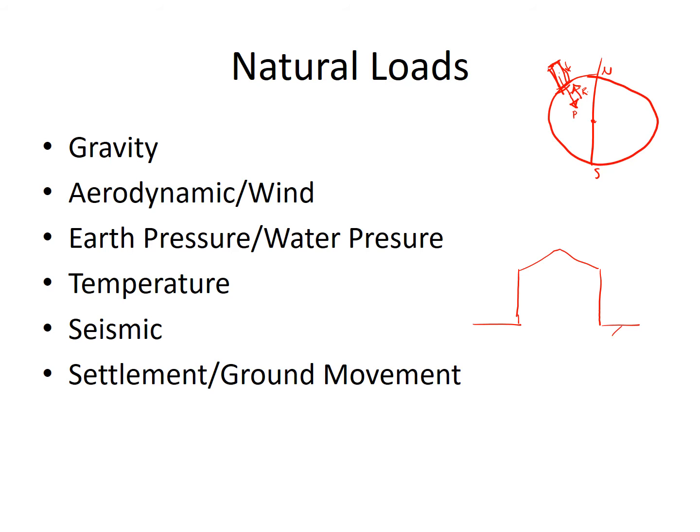that building is in an environment where there is airflow around that building, which is wind basically, and those particles of wind have a mass, and they are deflected so that their velocity is changed either by it being slowed down or stopped, or being deflected, a change in direction being a change in velocity. So that acceleration will exert a force. Force is mass times acceleration.